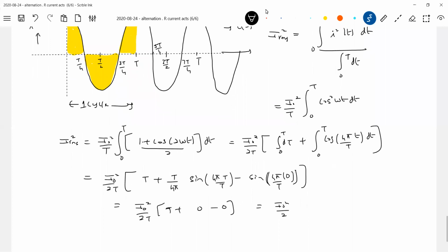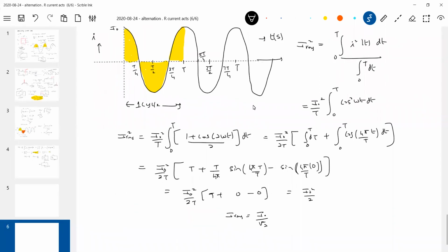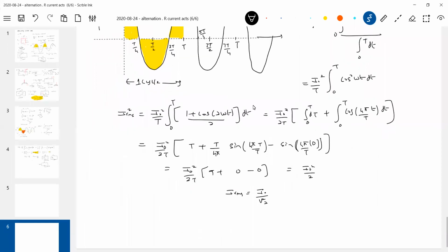So either it is cosine or sine wave, what is the RMS value? It will be the same. RMS equal to I naught by root 2. Please do notice these are very important. Small basics, because we just got carried away only by sine wave, cosine wave. What is the RMS value of all such signals where they have some phase difference between them?